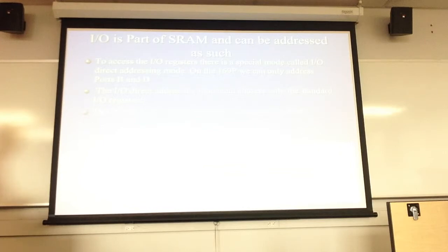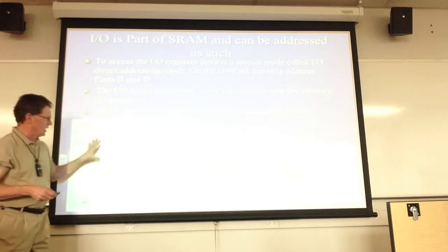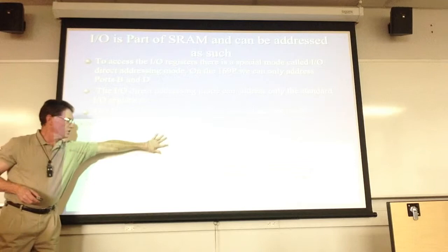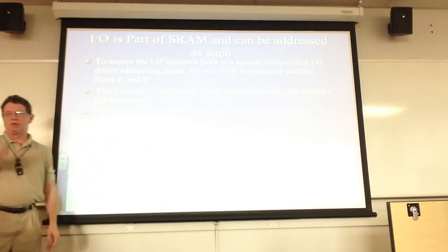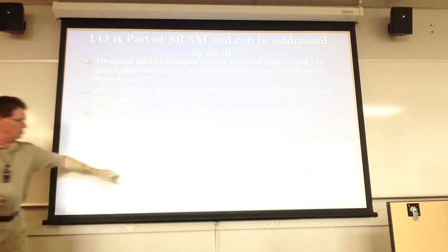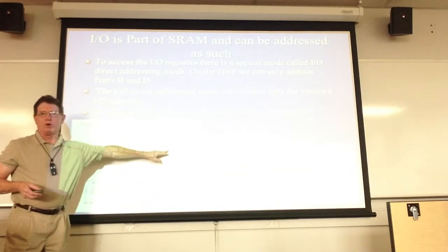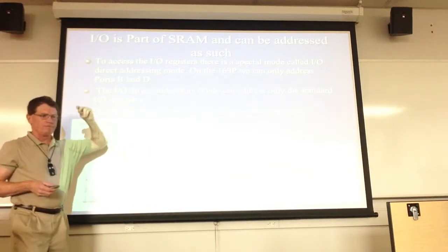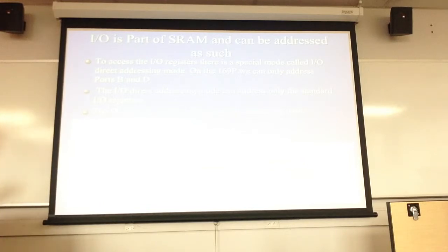And this is just out of page 21 of the manual. It's nice that the Butterfly board is a neat little thing where you've got all these things tied in with the joystick, the speakers, and all that stuff. Right now, we're just going to work with port D and port B. You have to remember that these ports are shared with the speaker also. I think I ran some code on Friday where one of the LEDs was tied to the speaker, so when you fired up that LED, you heard the speaker go off.